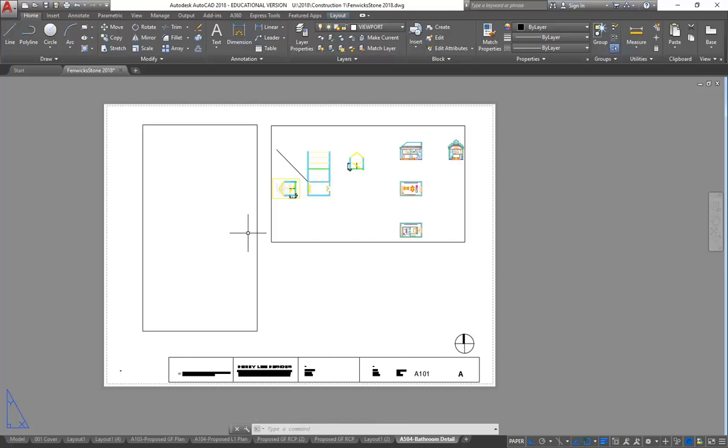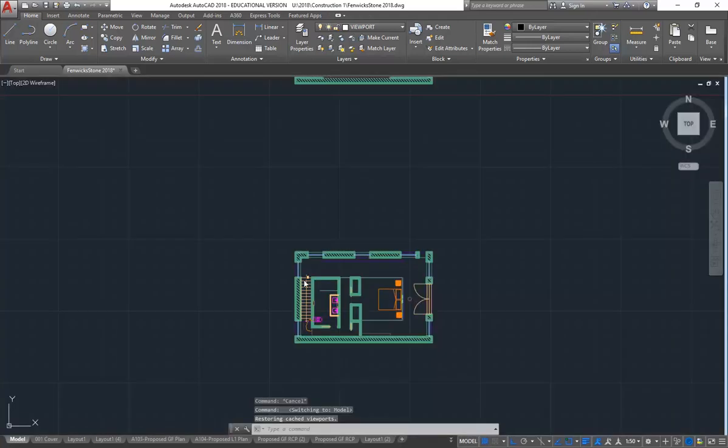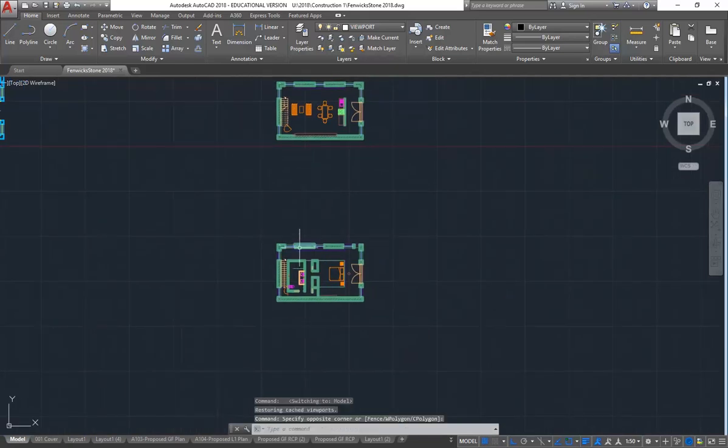helpful. Okay, so here you can see again, this will happen to you all the time. You'll have part plans where you've zoomed in on a certain area. If you've then moved that view, then you've got to go and fix your viewports. So again, I know that this one has been moved 10 metres down.